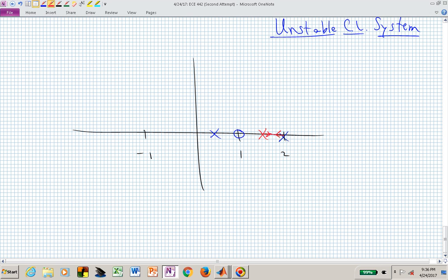And if we were clever, maybe, with our 0 location, we could cancel that, and now we have this circle with the 0 as the center of that circle, the breakaway point being the geometric mean of the two lengths, one length being between 1 and that, let's say, pole at 3/2, and the length from 1 to 2. So we have the square root of 1/2 times 1, or the square root of 1/2, or 1 over the square root of 2 for our radius.